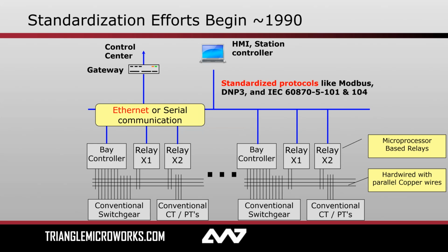Modbus, you might remember, was on the slide before. That did start out as vendor specific, but by this time it's become an open standard and has been adopted widely by not just the power industry, but the industrial automation sector as a whole. DNP3 and IEC 60870-5-101 are also developed around this time, and not long after, its successor, 104.